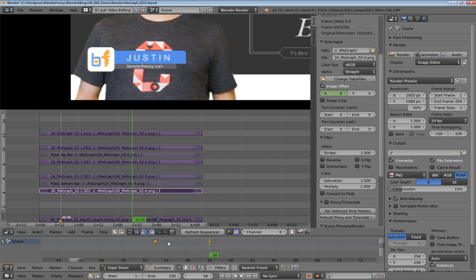Okay, and just with those two selected, hit S for scale and then type -1 and then enter, and that flips that around on the axis right here, the timeline cursor. And now you can see that these are the same, so it stays in the out position all the way until here, and then it goes back into the in position. Cool.